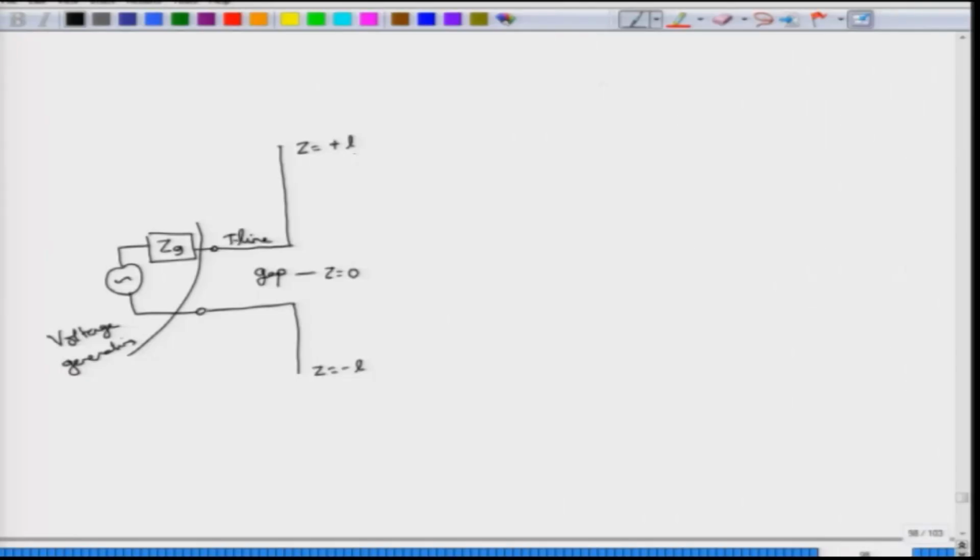But now the situation is not like that. The total length of the antenna is 2L as per what we have considered here, and is actually comparable to the wavelength of the fields that it is radiating. Because of that you cannot simply make the antenna current a constant. So, that leaves us one big question: what is the current distribution on the antenna?